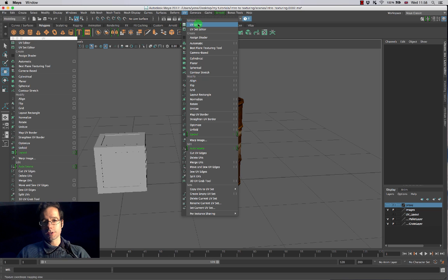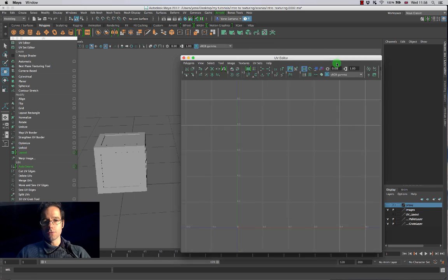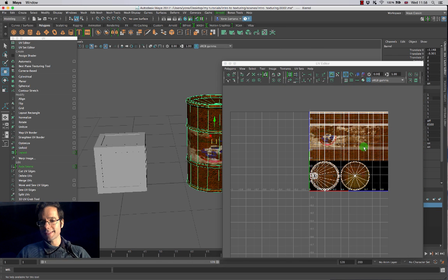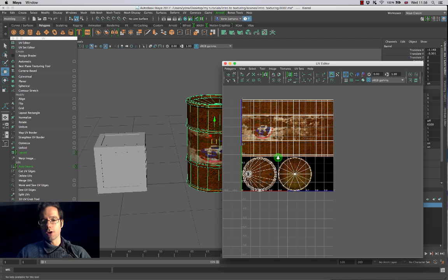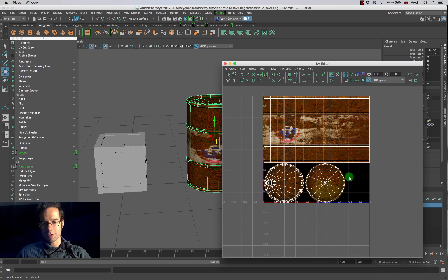The important thing about this exercise is that the UVs, at the end of the day, all fit inside of one single UV tile like this. And that's very much how we have to think about placement of UVs. They all should fit inside a specific space, because this is all the space that your scene can have for adding pixel perfect textures. Now this texture that I made here is roughly 1,000 pixels by 1,000 pixels, and its purpose is very much to give us the idea of where we should be laying out our UVs.